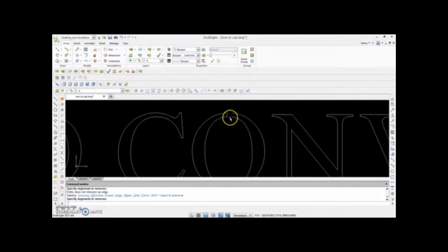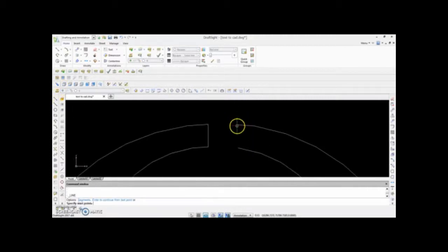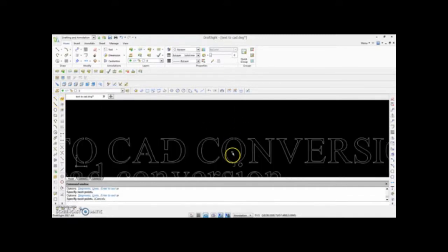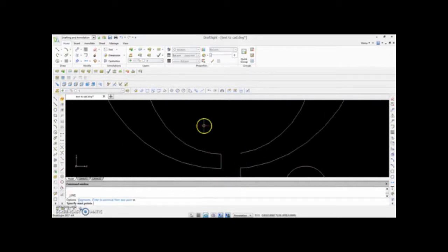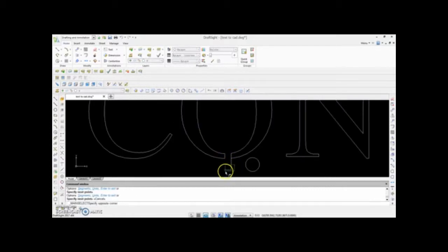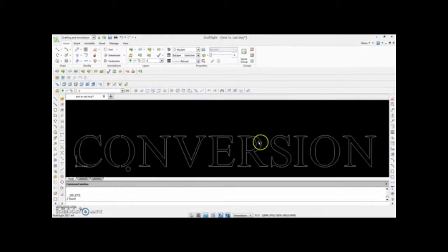Now you'll notice here that I'm missing a little bit, and it's actually deleting everything. That's because some of these little nodes here are not quite picked all the way, so it's not going to use those as a reference line. It really only gets complicated on curves, for good reason, because there are a lot of little line segments that make each one. Whereas when I did the A and the back side of the D, those were straight lines, so it's very easy to pick those sections.